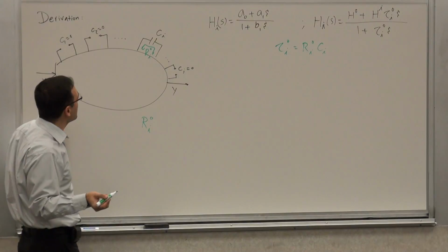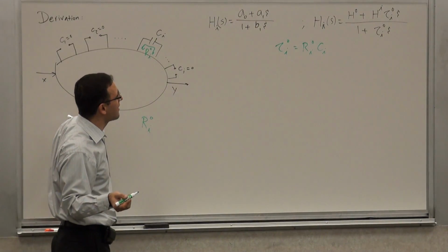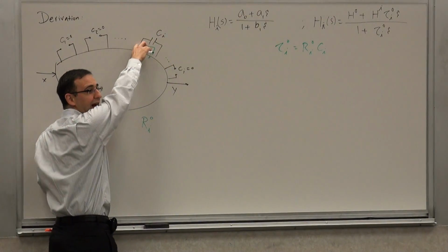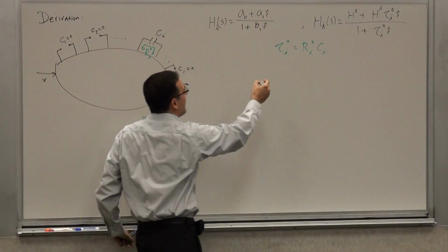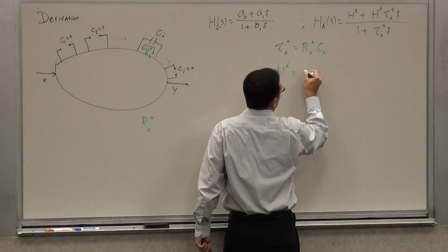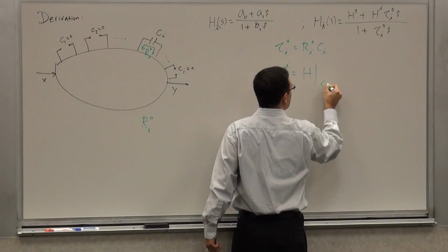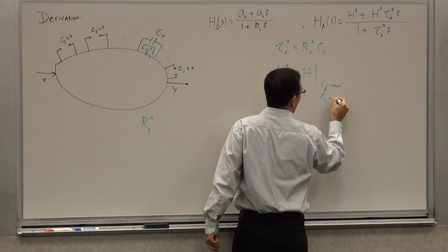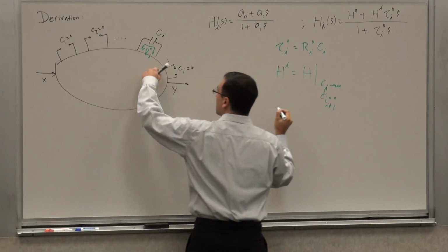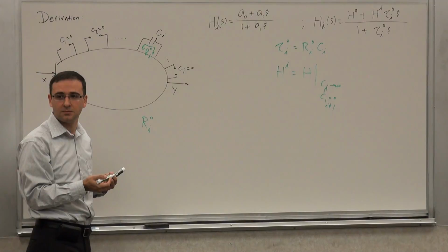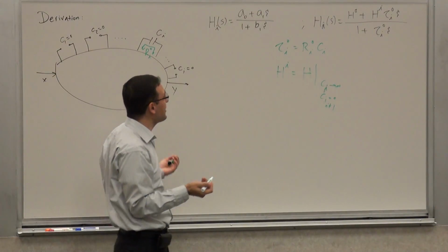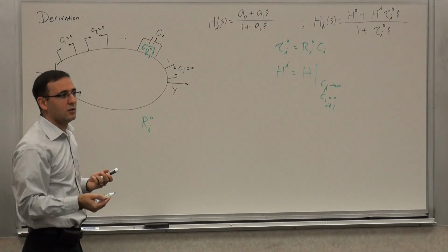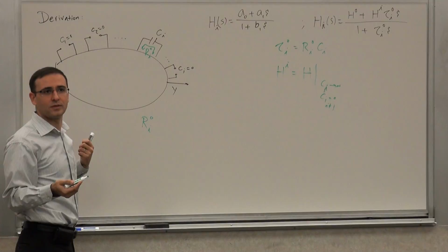And then I know one more thing. Okay, and what is the Hi? Hi is the transfer function by definition of this system when this guy is infinite value. Which is by definition again, so Hi becomes the transfer function of the original system when Ci goes to infinity, and all the other ones are 0. Right? Because we have already set them to 0, the way we define the system. So that's Hi. And H naught is the transfer function when Ci is 0, which is the transfer function of the system to begin with. Right? So this is a low frequency transfer function.